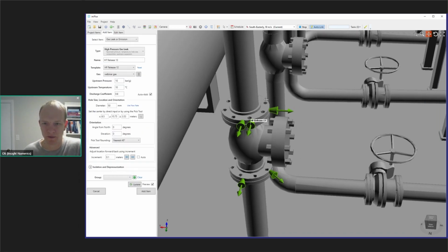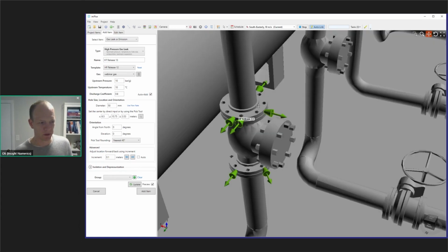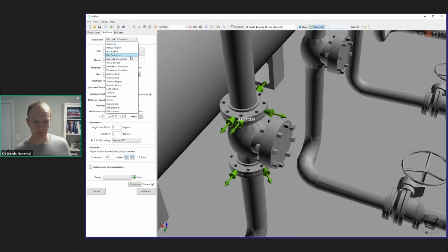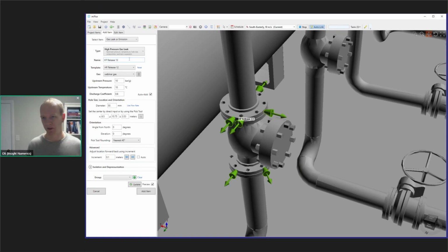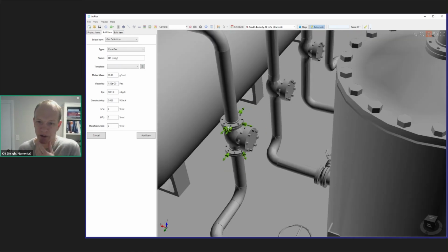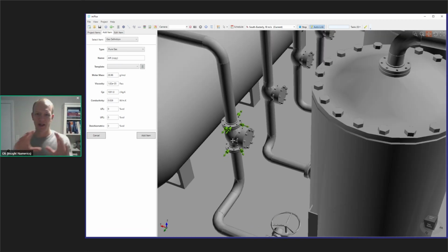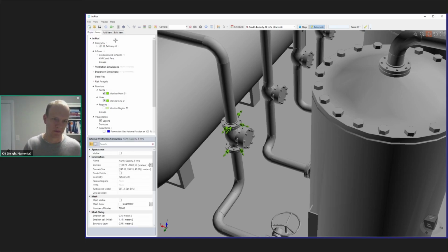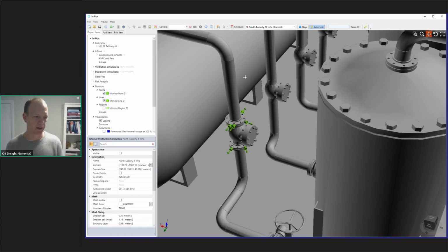Yeah, so if you have a dense gas, I'm assuming that's what the question is for, you can either have a multi-component gas like I just showed with different properties of the refrigerant, or you can create a new pure gas, inputting its properties into this form. Now, if you were to model a leak like that, you would again just use that fluid as the source of that leak, and you would see the dense gas slump towards the ground and spread. So it accounts for that buoyancy automatically, as a normal ideal gas.